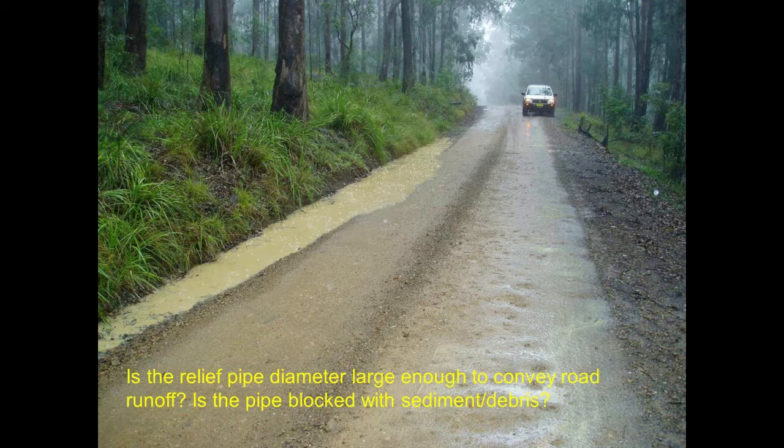Another thing to make sure is that these particular structures are cleaned regularly and maintained, because they can, as I mentioned, particularly those right angle ones, block up with sediment or debris, and then they effectively become useless. So that again is something that needs to be kept in mind. There's lots of tips that I could provide. I'll just mention a few more here.